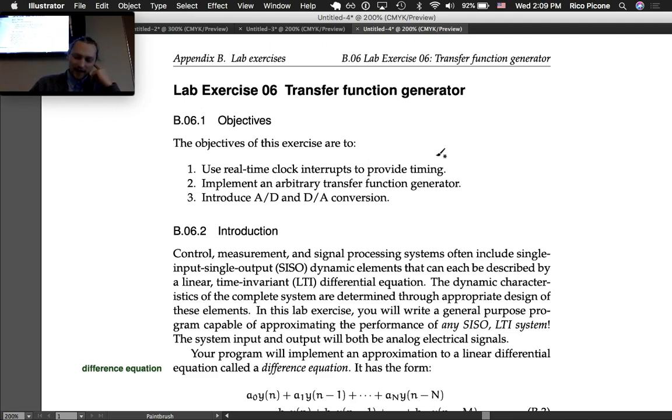So there's another way to do it that is preferred, which is you spool off a separate thread that does the timing, that goes through a certain amount of time, and then it sends an interrupt request when that timer dings, you could say. So every so often, for us it'll be every half millisecond in this lab, it will send an interrupt. And it won't have to worry about what else you're doing because it's in a separate thread. So that's the preferred way to do timing.